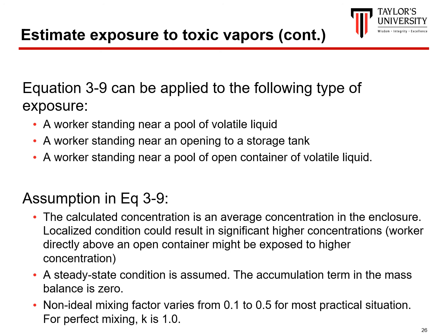And with these assumptions included, the calculated concentration is an average concentration in the enclosure. The localized conditions could result in significantly higher concentrations. So for example, workers who stand directly above an open container might be exposed to higher concentrations compared to a worker standing far from that container.